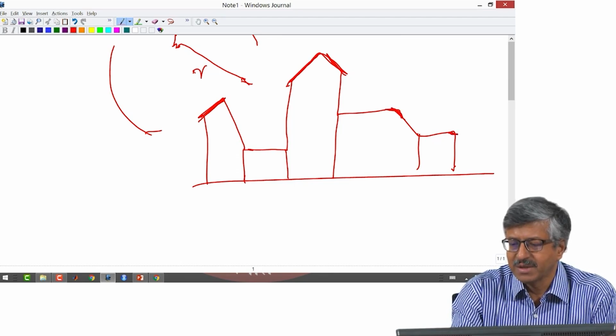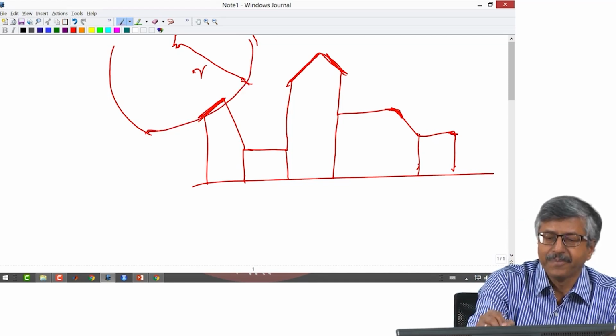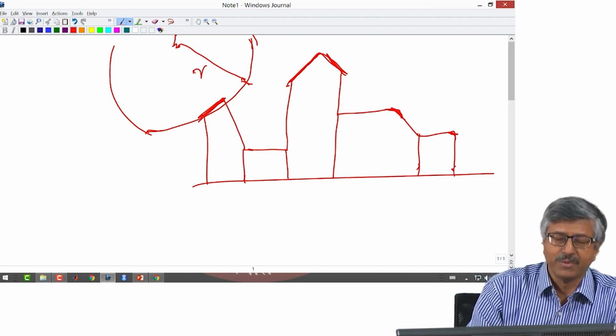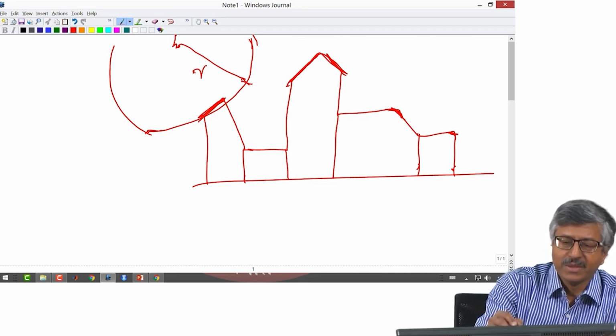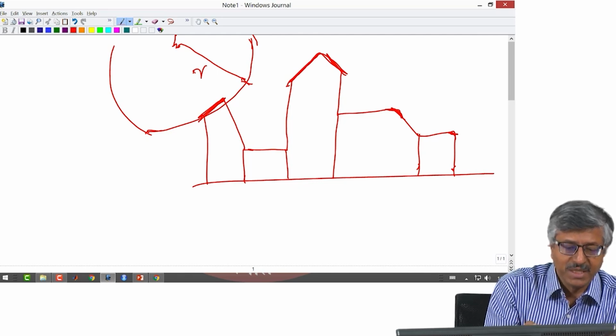So, likewise wherever the sphere is touching, you need to provide air termination. So, that is the rolling sphere method. The radius of the rolling sphere, the dimensions between the meshes, the angles to be used, all these things are given in the lightning protection standards.